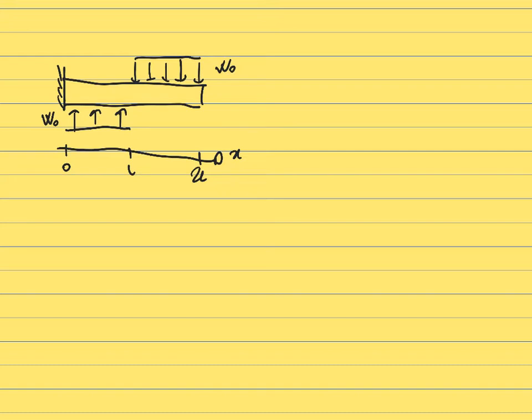And so we are going to see what are the different steps that are needed if we want to quickly show the trend of the internal shear and the internal moment. So for this, step one should always be to draw the free body diagram, which is what we just did. Step two, to identify the unknowns. So in this case, we have a fixed support at x equals 0. So a fixed support means that we have three unknowns.